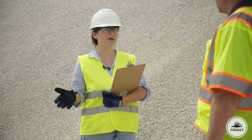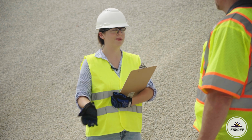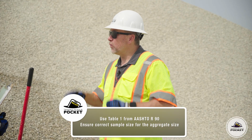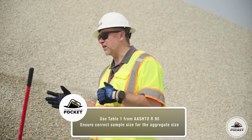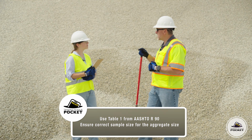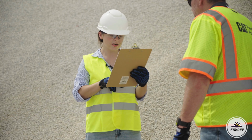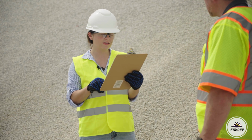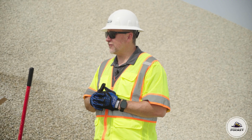So, like with the other method, we combine samples from 3 different locations to make a representative sample. Exactly. But with both methods, we need to make sure that we get enough material for the size of the aggregate that we're sampling. And R90 has a Table 1 that gives us that kind of guidance. Can you see what it is? Here, it looks like we need 35 pounds if this is 1/2 inch material. That sounds about right. So it sounds to me like you've got this concept down.